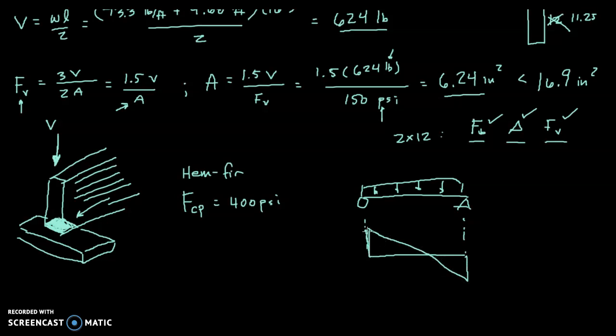Starts off with maximum amount of shear at one end, and then that decreases steadily until at the other end it's negative shear, has the opposite sense, but also maximum magnitude. So this maximum shear represents the reaction force at the end of the beam.